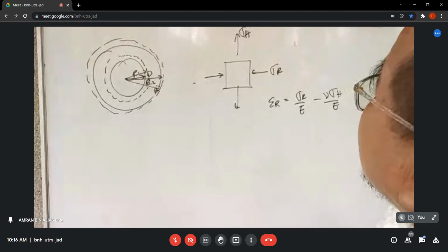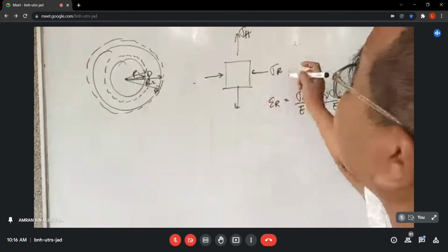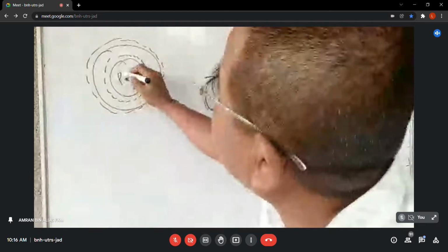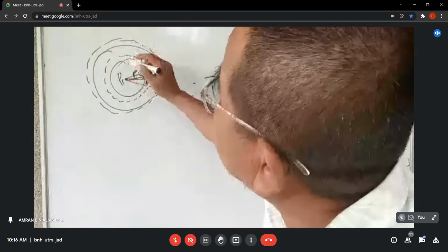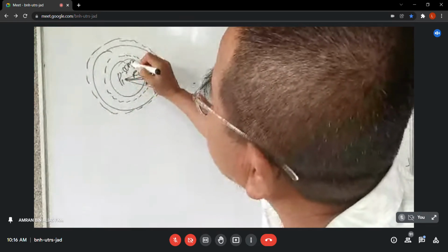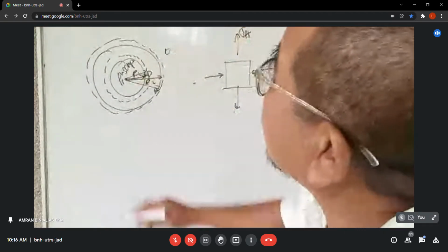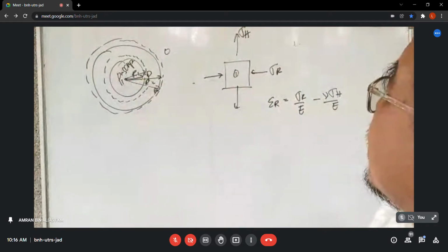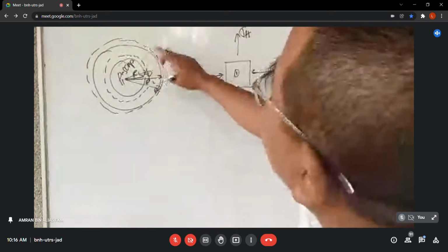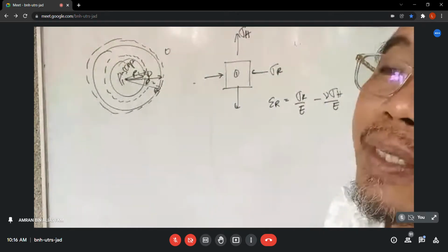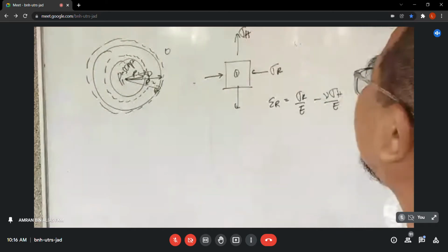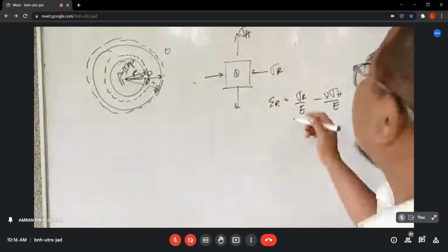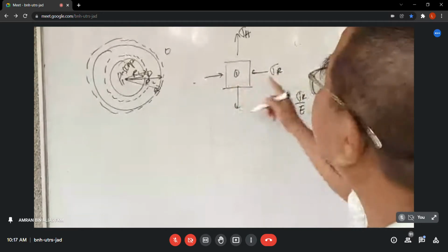Yes. So the strain in R is negative because we have a pressure inside. P1, let's say the value is 50 megapascal. Outside is 0. So this is inside here, position 1. So sigma H is positive, right? Yes, positive. Sigma R is negative, right? Yes. So let's say the value here is 50.